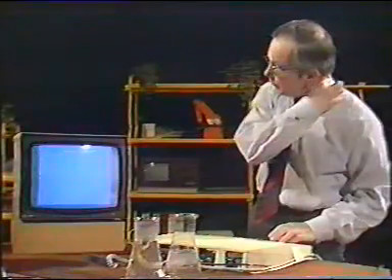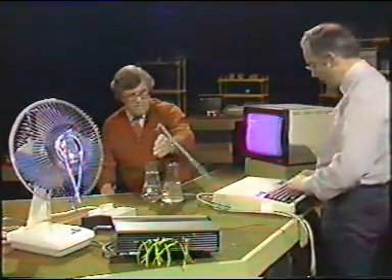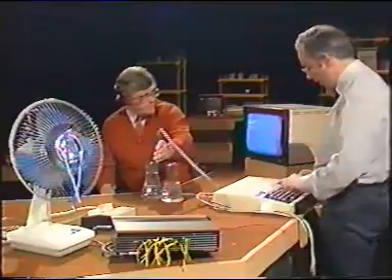In fact, we could stop the program running, and I could tell it to print, could you put it in the ice? Print adval 1, which will ask it to print the number that it's getting in from that input at the moment. And presumably a higher value if you put it in the hot water. That's right. So if we now ask it to print adval 1 again, you'll get a much higher value because there's a much higher voltage being produced by the temperature probe. So that gets it in.